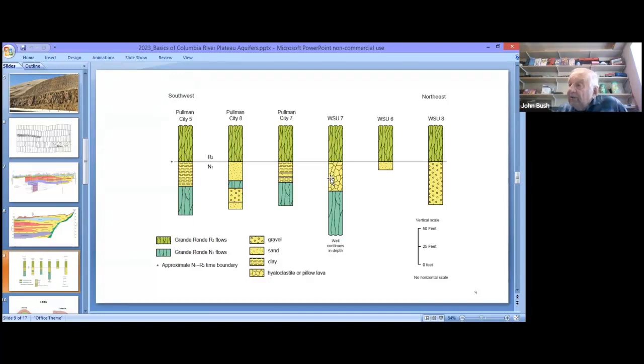Then you run a pump test to determine what kind of pump to put in, but you really don't know how much water came out of each of the zones, except where you stop is generally you've either added up to enough water or the last zone was your most productive. And so the point I'm making is that the Pullman aquifer system is not just basalts, it's being fed by sediments, and they play an important role in that system.